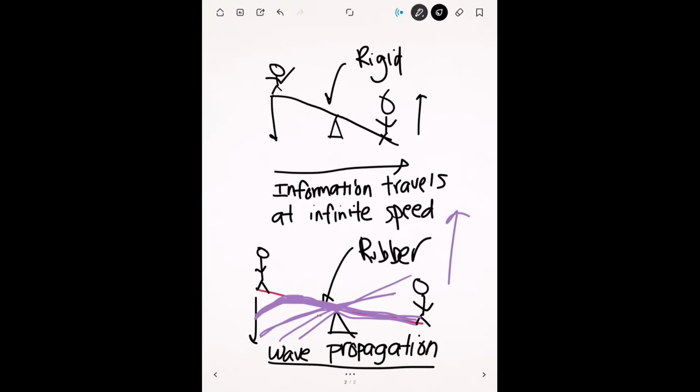Okay? It's definitely a weird concept to grasp at first because it's not like the pressure is traveling with the blood. Okay? It's traveling at its own independent speed, and it's traveling along the walls. Okay? But it's not instantaneous, so it has some finite speed. Okay? And the only way that you're going to capture this wave propagation phenomenon in your simulations is if you use a deformable wall. Okay, so let's see how we set this up in SimVascular.